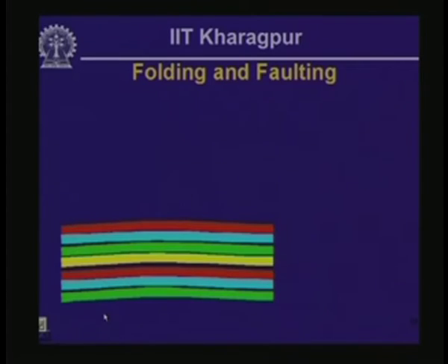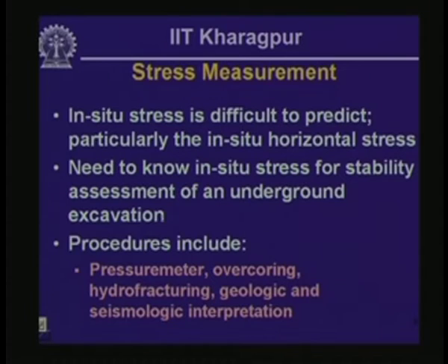Now what we could also do is to pump water in within the joints and pressurize at high pressure, and this process is going to actually start opening up the joints when the state of in situ stress is overtaken by the pressure which is there in the fluid that is being pumped in.